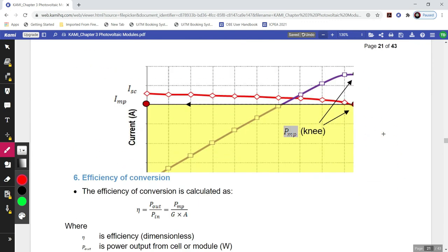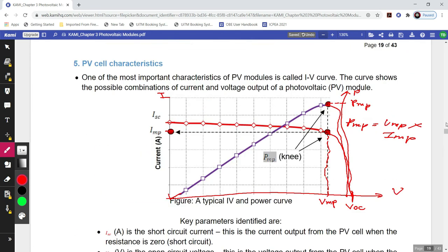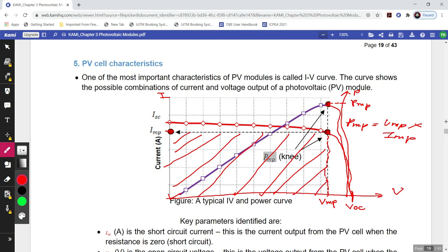We also have an error here on the figure. So your fill factor is here, the squareness of the IV curve. This area only. So it's the ratio between IMP multiplied with VMP over ISC multiplied with VOC. So here is the area, the squareness of the IV curve.